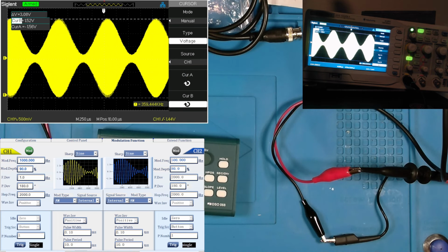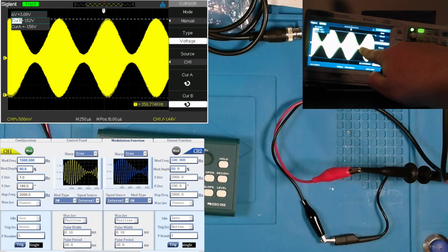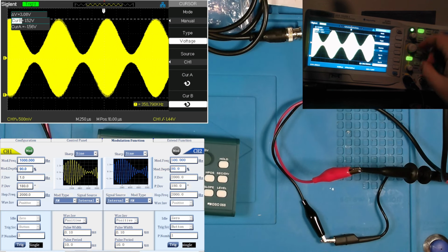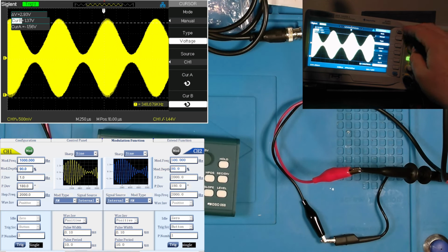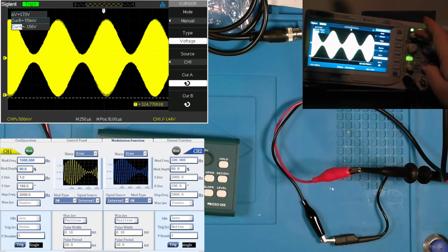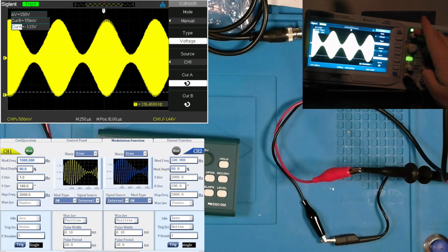And now that I have that written down, now I want to measure where I'm closest together on my waveform. So let's move channel B down, my cursor to right there. And then channel A cursor, we're going to bring it up to right about here.